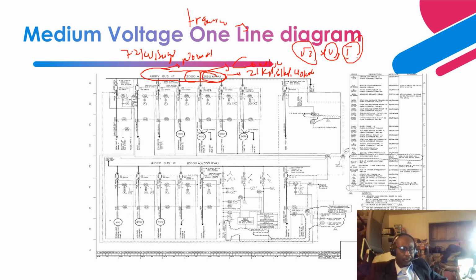Okay, so like I indicated, this is a double-ended switchgear, so basically it has two buses, one bus here and another bus here. These are all your loads that go to motors. As you can see over here, these are the horsepower ratings of the motors: 900 horsepower, 900 horsepower, 400 horsepower, 400 horsepower, 400 horsepower, 450 horsepower, 400 horsepower.